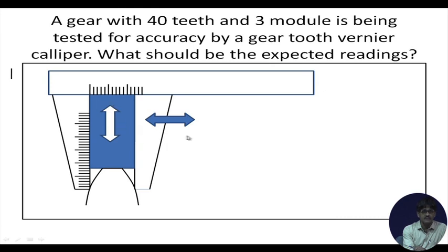That means this particular caliper jaw can move and accommodate different dimensions between these two jaws. At this moment, it is measuring this particular distance. This is a gear tooth. Corresponding to these two jaws, there is another moving slide, moving in between, which can be moved out or moved in to measure precisely this particular distance.